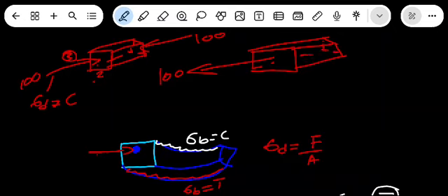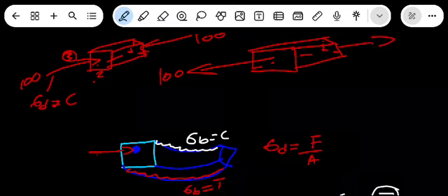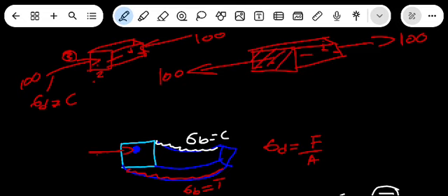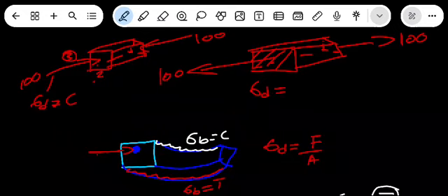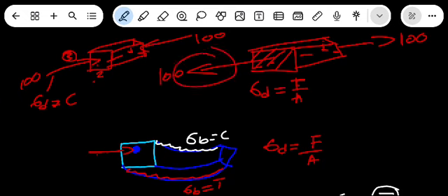So you have the pulling forces here, 100 Newton. So this is direct. It's acting on the cross section, isn't it? That is the direct stress. We call this direct stress. But this direct stress is force divided by what? By area. But because it's acting there, we can call this the tensile one. Tensile will be positive. Take it as positive, please.